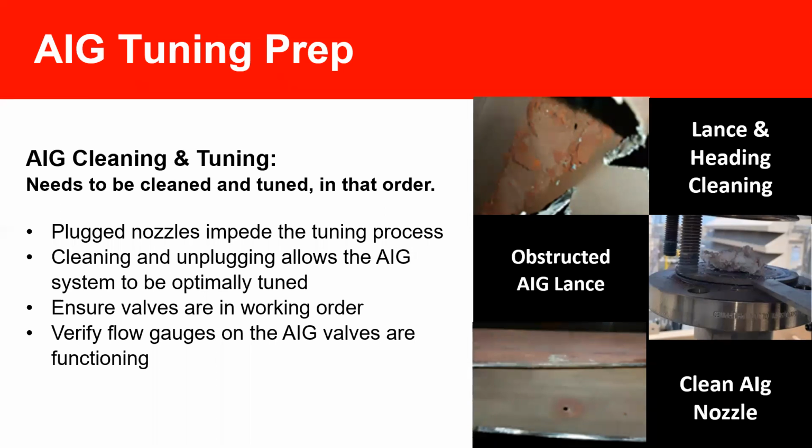The middle photo I just experienced recently. So I was tuning a grid out west, and you can see how sunny we are. And we had a whole zone that wouldn't react to any kind of nozzle change. So we took the unit down and took a look at it, and you could see sitting on the orifice plate like a frying pan is a 2-inch by 1-inch brick of catalyst depositing. This particular unit received a bad batch of ammonia, and it ended up fouling every available surface it could find. So that would explain why none of the valve movements were working to tune this particular unit in, which is the next thing that needs to be in working order.